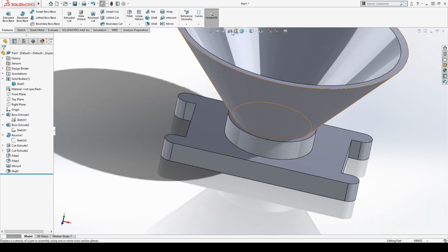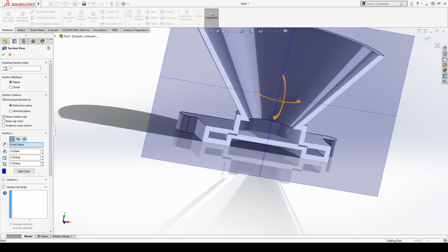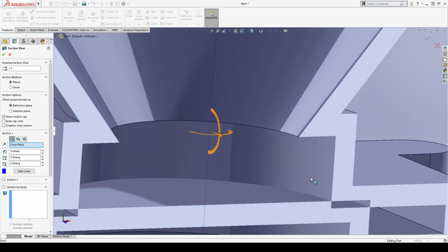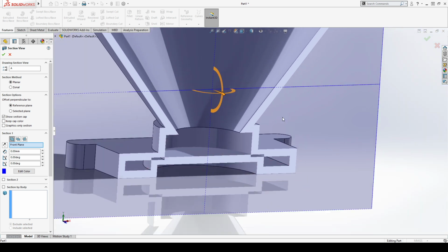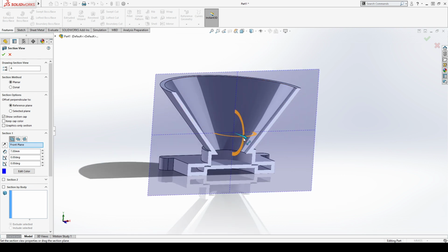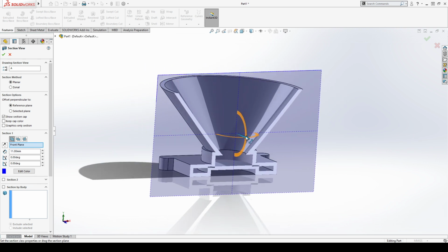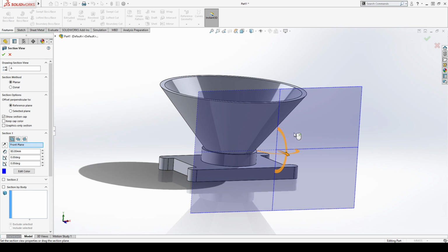I'm going to show you a section view of what it did there. So it went through everywhere in the part and made a wall 3 millimeters away and cut everything else out. That's what the shell feature does. It's really handy for creating thin geometry. You just basically model, again, kind of like that glass. If you know it's going to be a constant thickness all the way around, just create the solid part, delete the face that's going to be open, and it creates a shell of everything else.